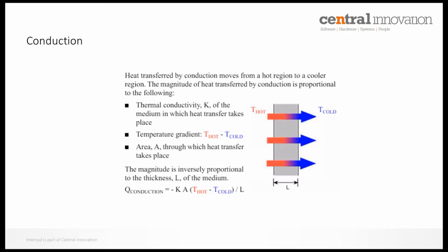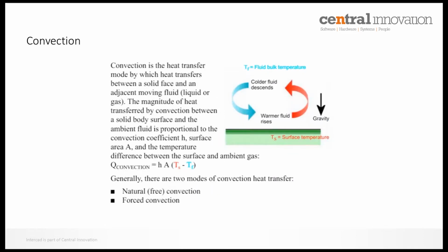And the rate of heat transfer is primarily decided by the material properties. So it's quite crucial that you get your material properties from a reliable source before you set it up, so that you can approximate a realistic output from the simulation calculation. Right. So later on I'll be focusing more on those specific material properties, and let you know how each one of those matters and how to select each property to be entered into the database before you create a new custom material.